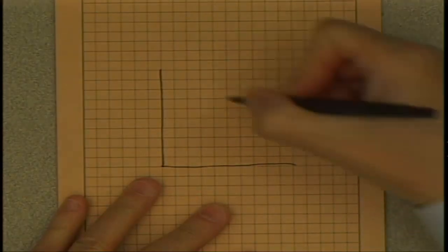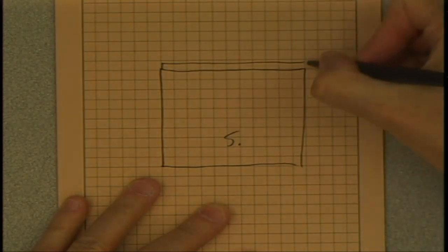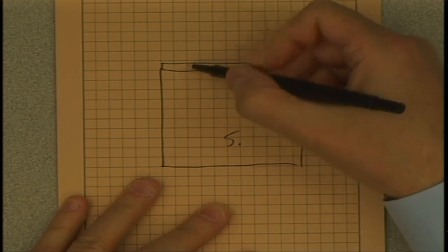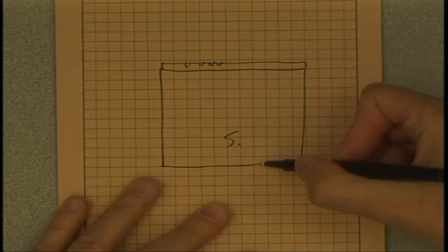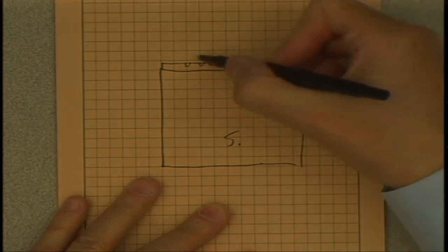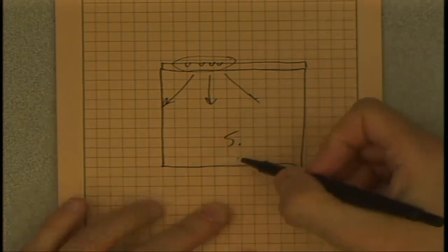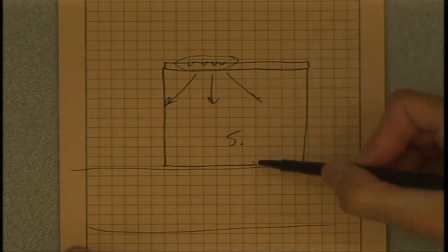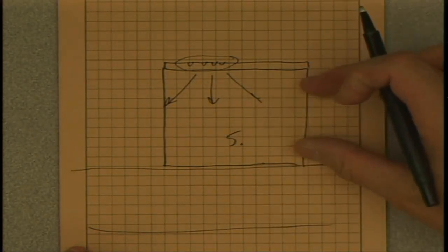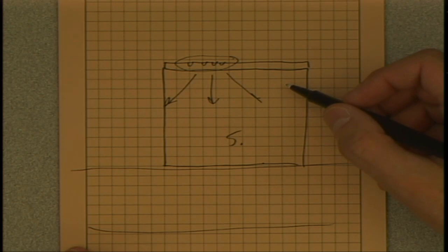When you have a die, let's say this is the thickness, and this is silicon here, and you have all this junction engineering going on at the top. So this is the epitaxially grown silicon, and it has the trenches in it and so on. This big chunk of silicon doesn't really help you dissipate power. I'm creating power up here in these junctions. I need to spread that heat out and get it to the back plate, which is this big thick slab of copper, right? I have to travel through the silicon. So if I have thinner and thinner silicon, I'm better off thermally. So for the same die area, I can dissipate more heat.